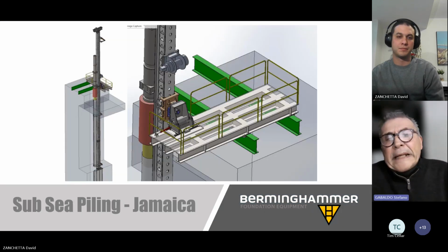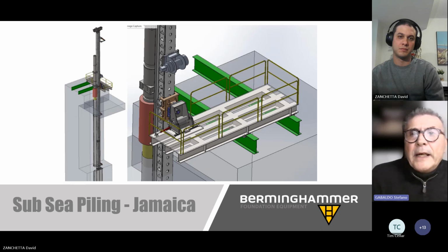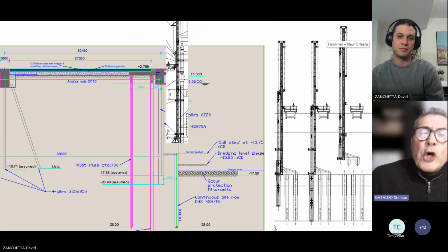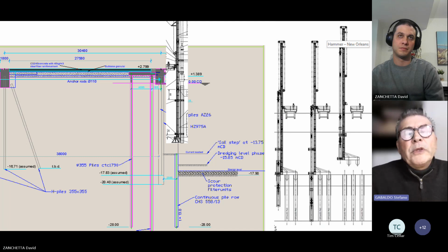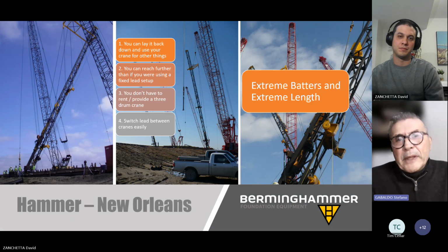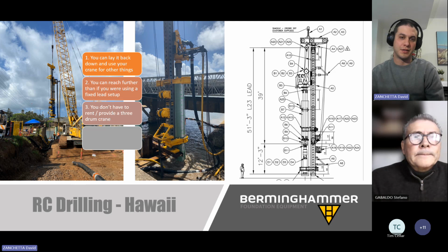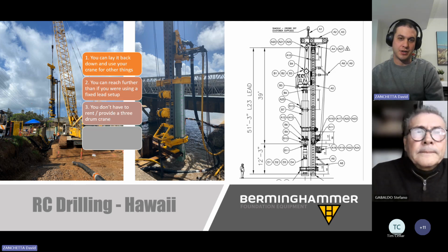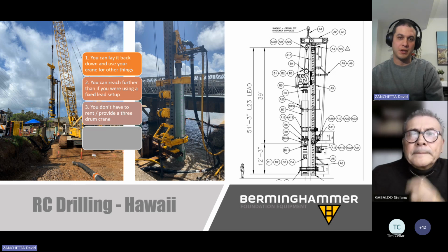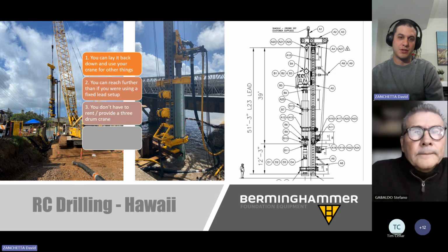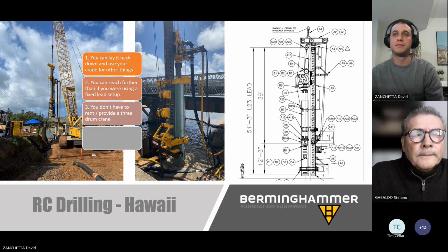Also to add, if you were in a casing advancing system, we cannot clamp the pile, so we would need to react against the template itself. Yeah, you can see in this photo as well, they've got a template and it consists of essentially an I-beam sideways that the foot then is inserted in. And this was our BRC 100 on that one. So it was a template that the foot was inserted into to hold the torque.